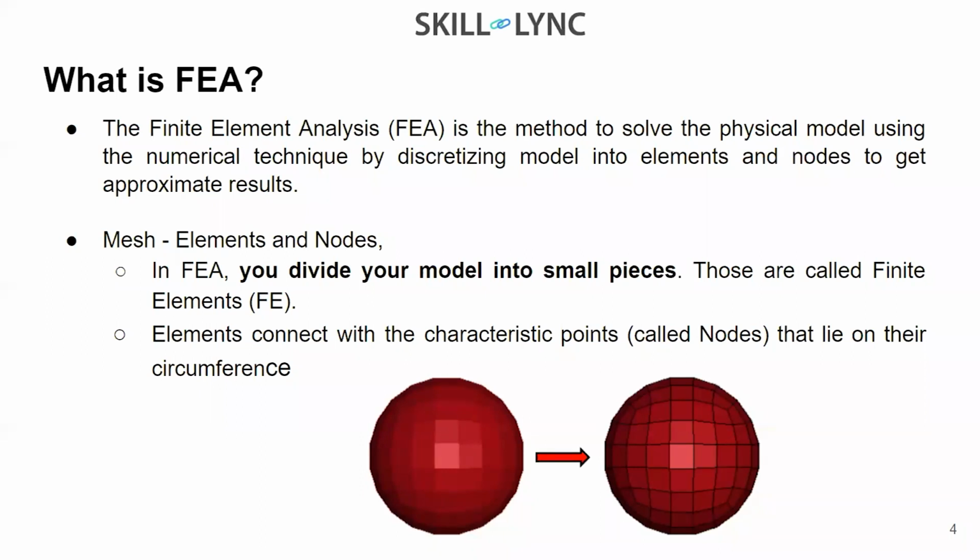Just remember this key point: numerical technique, where we have a physical model and we discretize this model into a finite number of nodes and elements, and apply boundary conditions to get approximate results. I'm repeating, these two points are very, very important: FEA is a numerical technique, and we get approximate results out of the simulation. Why approximate? I'll tell you.